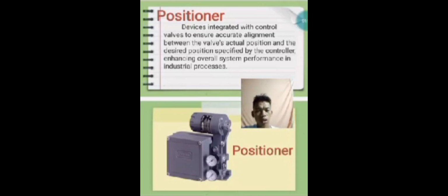The flapper position is changed, and the nozzle pressure changes, operating a pneumatic relay. At this point, we simply have a pressure to pressure transducer for the input. To make it a positioner, we must have feedback. The feedback ensures the control valve is responding to the input, and the valve position corresponds to the given input.